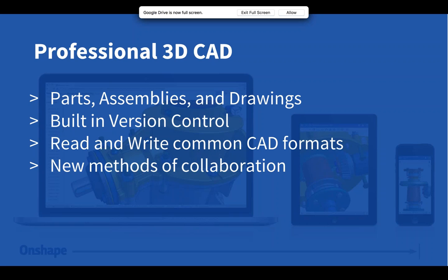So evolving very quickly, but we also have some features built in that makes the process simpler. So with Onshape, you have built-in version control. You don't have to do a separate data management system or separate software to manage your files. That concept is gone in Onshape, and we have an integrated version control. It's built into the core functionality of Onshape.